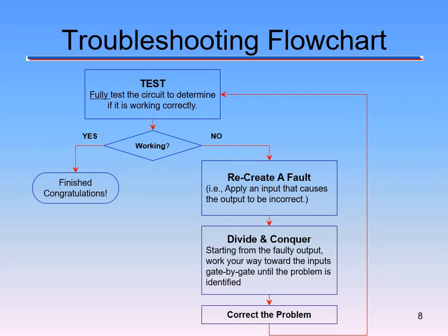So you want to make sure that, when I turn switch 1 on or off, is the signal coming out a 0 or a 1? And then is that correct? Is the logic gate reading the signal incorrectly and putting the wrong signal out? Like, is the chip fried? Or is there a short in the breadboard? Did I grab the right chip?